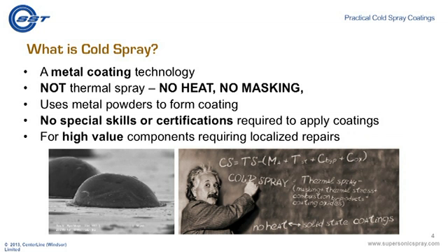Now, before we get into the formal definition of cold spray, I want you to imagine something for a second here. Imagine a control unit about the size of a 2-drawer filing cabinet with wheels on it. So it's portable, you can move it around. Also imagine something about the size of a handheld hairdryer, with a 1/4-inch exit nozzle. Connecting these two is a 1-inch diameter flexible conduit. Imagine coming out of the end of that 1/4-inch nozzle metal particles traveling between 300 and 700 meters per second directed towards a target. The target is either a metal or glass. You're going to make a coating on that substrate. That's basically what cold spray is.